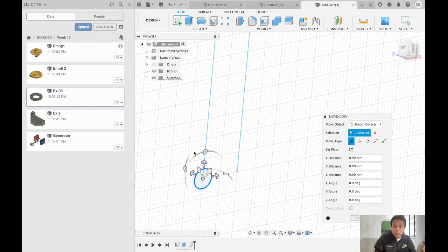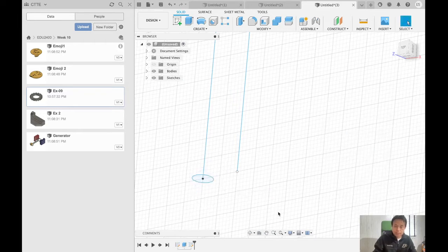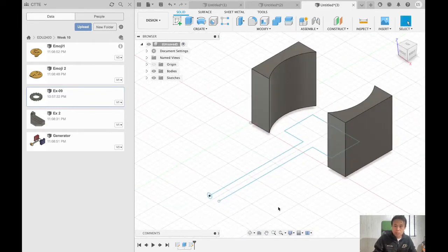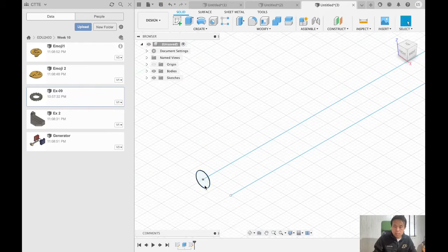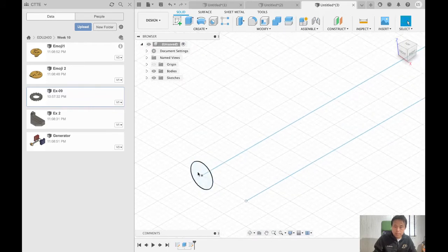That shows this window and these arrows. This is a rotating feature. We can rotate about the XY plane or YZ plane, but I'm going to rotate to this angle, so 90 degrees, and click OK. Or you can type 90 degrees, and you can play with this. Zoom in, so that is 90 degrees from this coil.